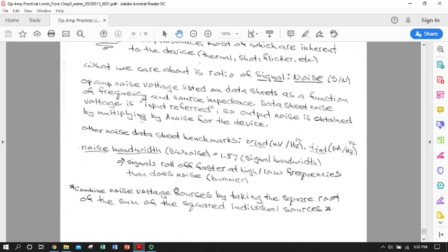That's not a noise per se, it's an error signal, something we don't want. We were able to add that with straight addition. A noise source we would add by squaring it, squaring the next noise source, squaring the next noise source, summing them together, taking the square root. And that would be the noise that would go into our signal to noise ratio.